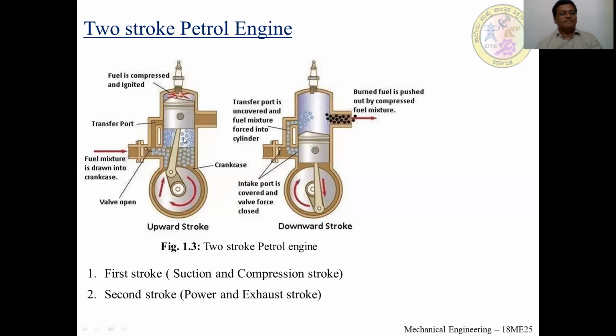As for the valve arrangement during this stroke, the inlet port is open, and the transfer port and the exhaust port are both covered. The ignition of the fresh charge takes place at the end of this stroke.